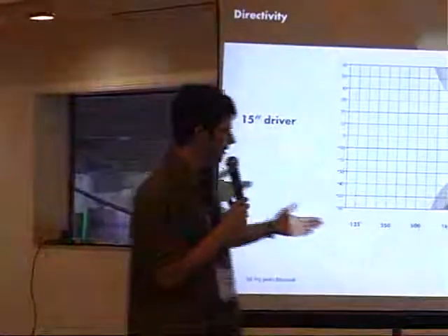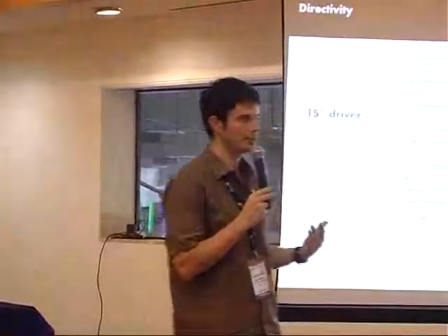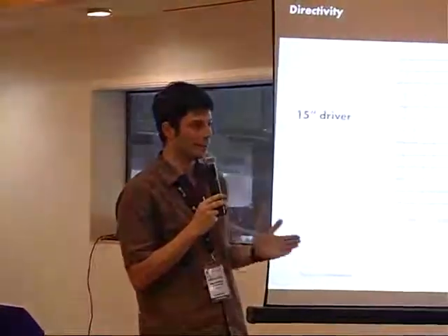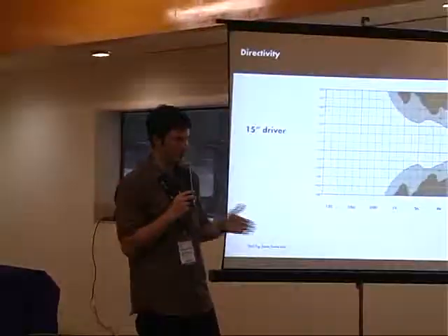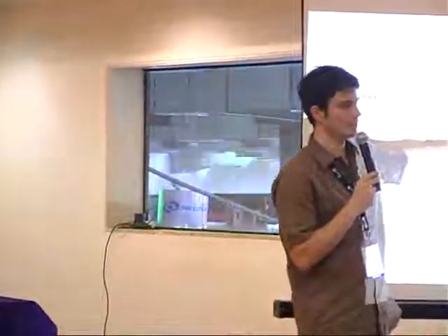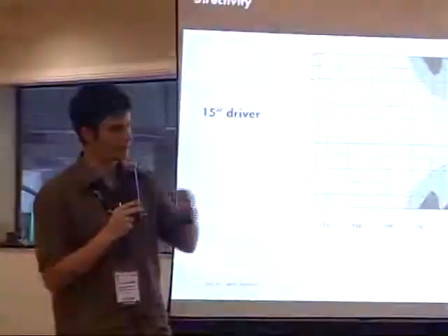And since the whole industry basically has come to the convention of specifying the minus 6 dB angle, this is why we take 6 dB separations in terms of level. So this is how we can see the whole picture in terms of directivity of a driver, a box, whatever.